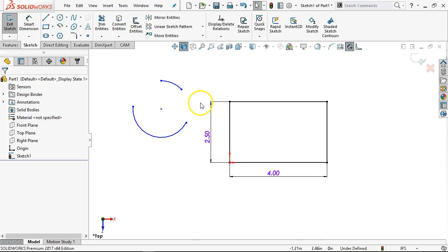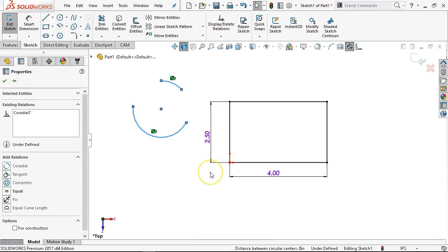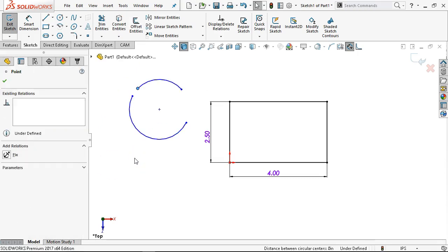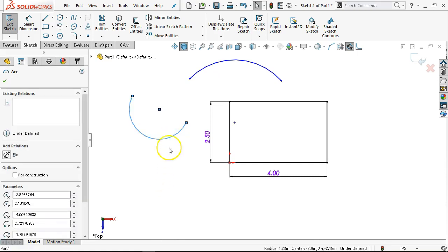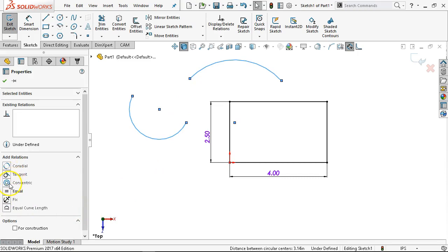I have to go back and verify every time I get that question, but usually the last one that I selected becomes the stationary, and the previous arcs all follow the last one. So if there is intent, and that one, I didn't go back far enough. So let's go ahead and select that one first and test the theory. All right, try again, and go concentric. That one moves in relation to that one.